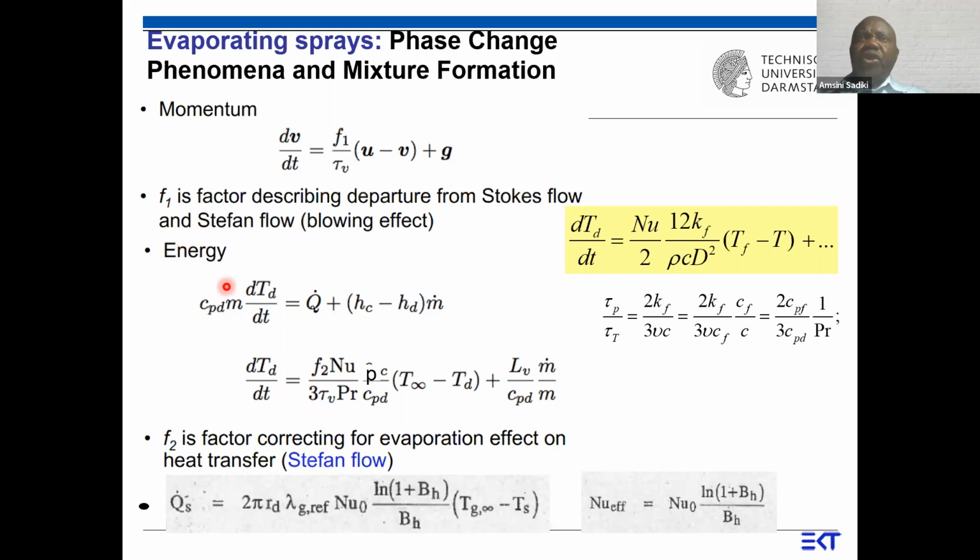We have the energy equation, with the F we provided here. From them we can have the expression for the temperature of the particle. It is derived from what we had, and assuming this relationship here, we can go from here to this expression. This introduces the dynamic relaxation time.